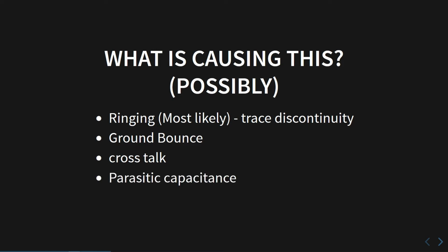And there's parasitic capacitance, in the sense that there's capacitance that is not modeled into the system, but it exists, and now you want to eliminate it. Every trace will have some form of impedance, inductance, capacitance and resistance. But if the values of those are causing problems, and they shouldn't be, then we want to address them.